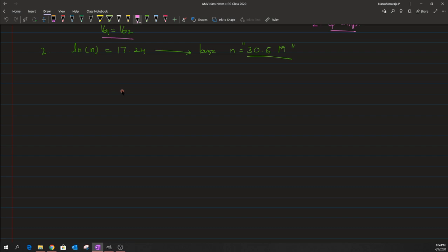As said, we are going to use a supply independent biasing. I guess you still remember that the supply independent biasing circuit is a combination of a PMOS current mirror with an NMOS current mirror, but we would make this PMOS current mirror have the same W/L factor. If I label this as M3 and this PMOS transistor as M4, and I make the ratios of M3 and M4 common, then the currents flowing through ID3 and ID4 will also be the same, right.